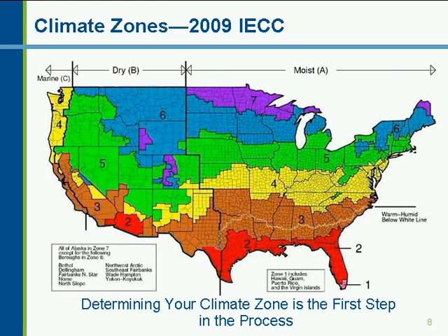The code requirements for the building envelope are based on climate zones. The colder the climate or the hotter the climate will basically dictate how much insulation or the type of glass that has to be put in the building and the properties of that. So, for example, you have climate zone 1, which is down here in the tip of Florida, all the way up to climate zone 7 in the lower 48, which is upper Minnesota and the northern part of North Dakota. Climate zone 1 is going to be a hot climate. Climate zone 7 is going to be a cold climate.